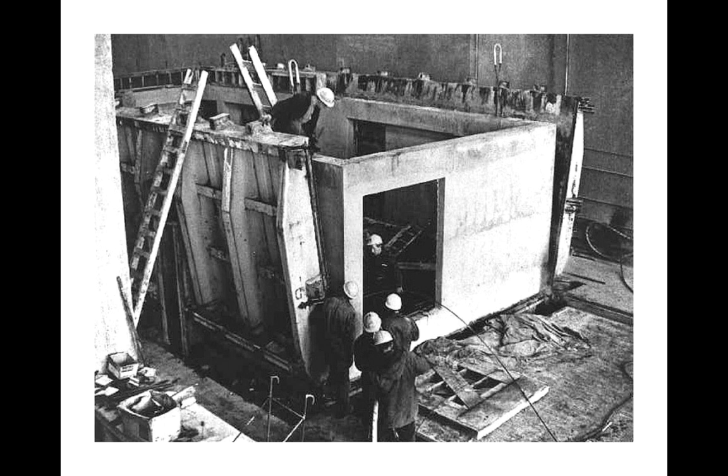This is what a precast factory looks like. This is a particularly large precast unit, but you can see that there are things that are analogous to what you would see on a concrete job site. There is formwork that, of course, is molding the concrete. There are inserts that go in to block the concrete flow and to create openings for doors and windows. There are embeds that are going to connect with steel in other units so that they can tie these together.